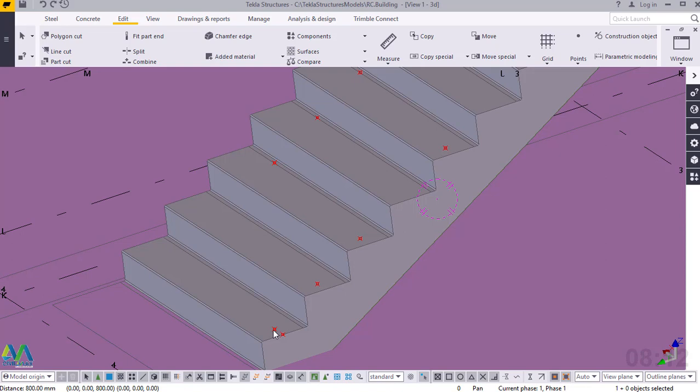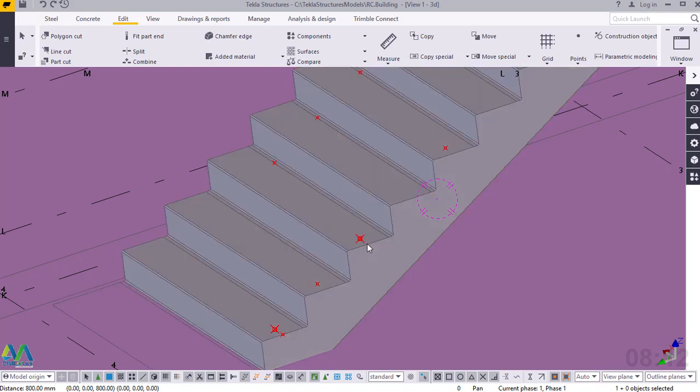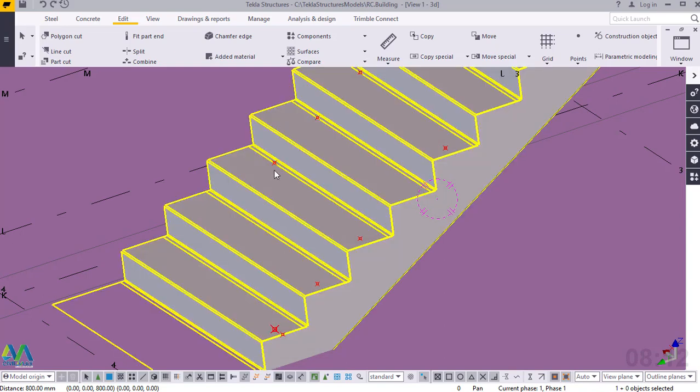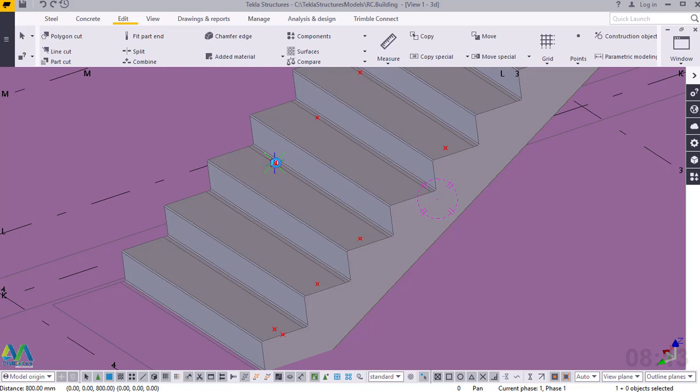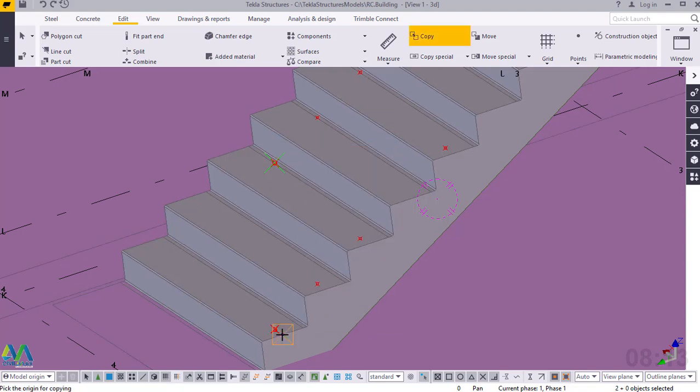So the moment you've done this, now we want to copy these points to every thread, but we will omit one step after the other. We omit one thread, then place it on the midpoint of another thread, like the way I'll do it now. I'll pick these together. I'll pick this and press Ctrl and pick on this. Then I'll right click and come to copy. Then I'll copy it from the midpoint. From the midpoint here, I'll snap right there, and I'll skip this step.